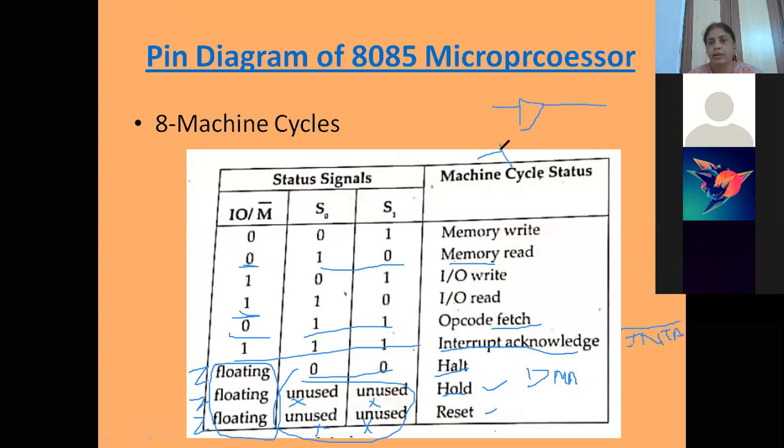नॉट गेट. नॉट गेट में आगे एक ये बबल होता है ना, तो here we are giving A, so what we are getting here? A bar. Okay. And if you pass it again through one more not gate, then it will be A double bar and again you are getting A. ठीक है. तो इन दोनों को combine करके we are getting this buffer. Clear? So this buffer is giving the same signal A here and A here, but after holding that signal for a small period of time.